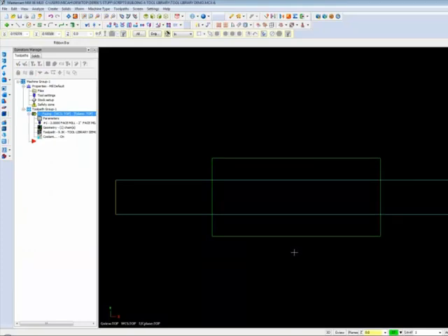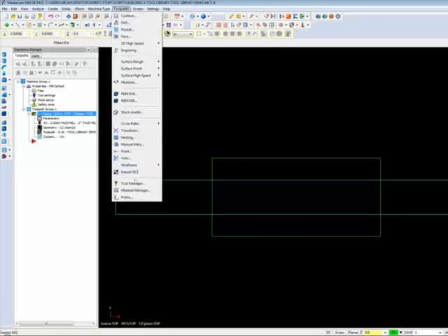Now that we've begun programming tools into our tool library, we can program toolpaths with far less work than before. Let's add a few more common tools to our permanent machine library, starting with the 1/2-inch end mill. Select Toolpaths, Tool Manager.